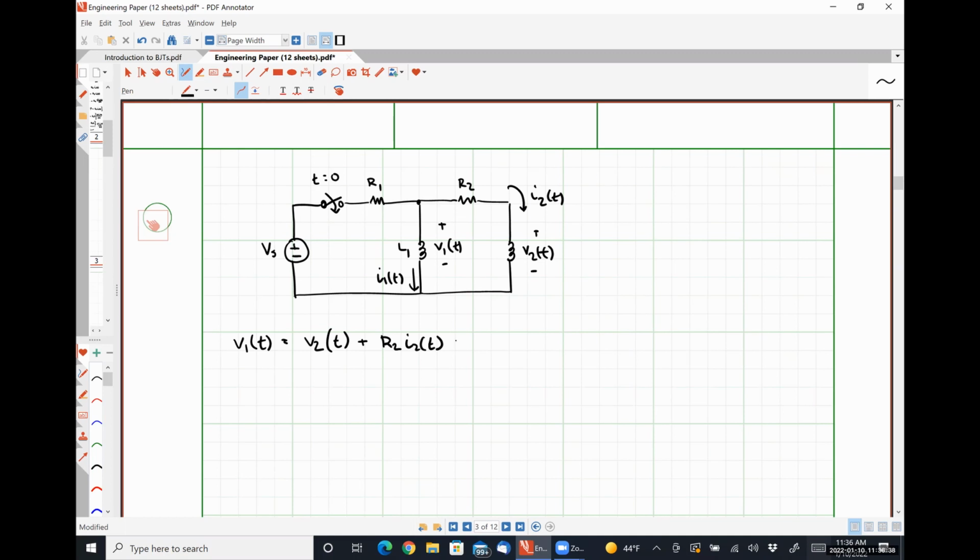So right now, this equation only has three terms, but only one of them is expressed in terms of something that we can actually use, right? We have two inductors, and we are going to want a second order differential equation in terms of either I1 or I2. So Sarah, what do we do to change those voltages to something useful, which are our inductor currents? Right. The voltage drop across an inductor is simply the inductor value times the derivative of the current.